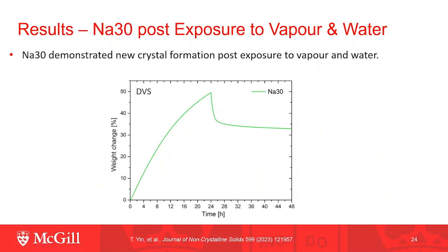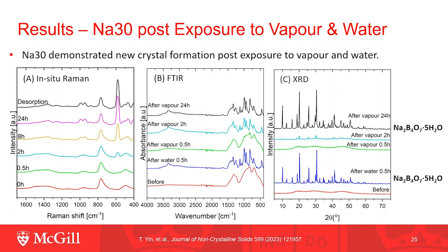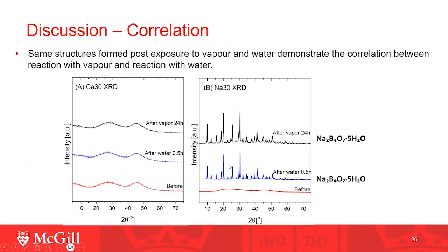Well, for sodium-30, it has much more weight change after exposure to vapor. And from in-situ Raman and FTIR analysis, there is new phase formation after exposure to vapor for 2 hours. And this new phase was identified to be crystal by XRD. We can also say the same crystallization also occurred when immersed in water for 30 minutes. We can say calcium-30 has no structure change for both post-exposure to water or vapor, while sodium-30 forms the same crystal when exposed to water and vapor.